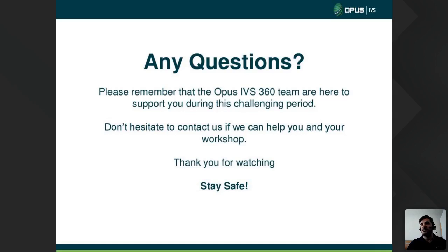Right, Gil Scherer has asked one of the questions, saying, how do you test the cat? Well, typically on that 1 litre EcoBoost engine, I would put the emissions tester on the exhaust and check the condition of the emissions and see if the cat is doing its job or not. If the emissions are within spec, Gil, then it leaves you with having the O2 sensor after cat tested. But if the emissions are out of spec, then you know the cat is not doing its job, and most likely that's the reason why the fault has come on, saying that the cat efficiency is below threshold. Hopefully that will answer your questions.